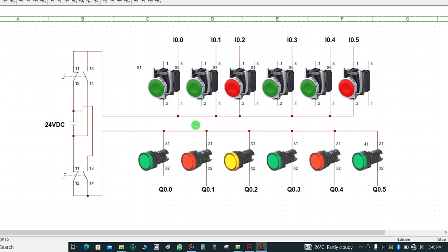So carry out this connection and enclose them in a box and provide the outlet plugins and the inlet plugins. This is your input and this is your plugins or tagging to communicate with your PLC. This other side is also your tag from your PLC to your output module. All right. So this is how you design your workstation.